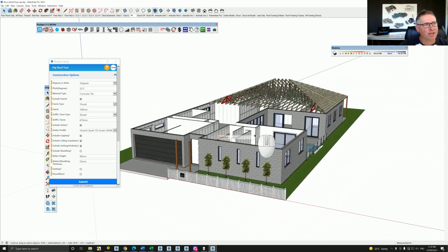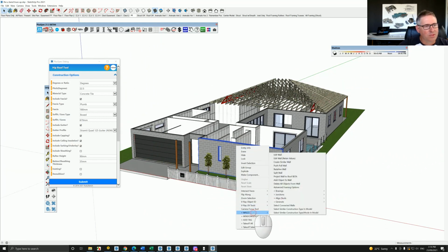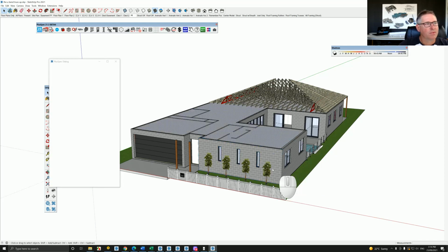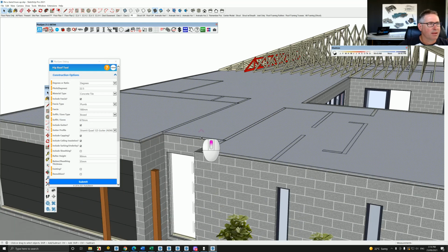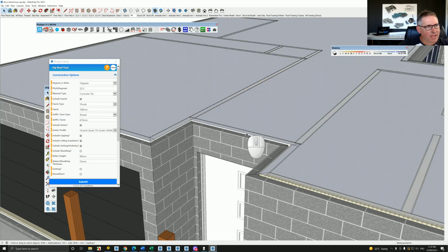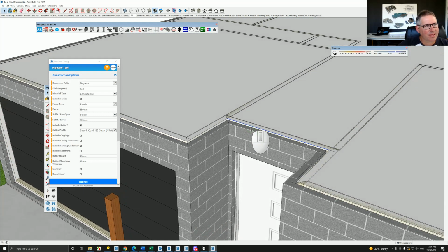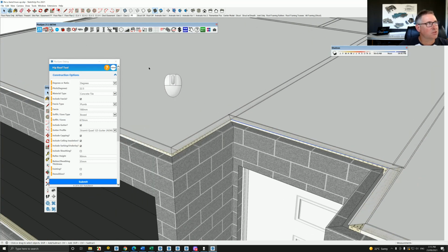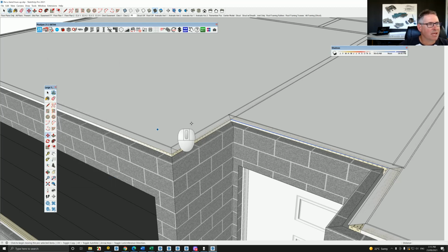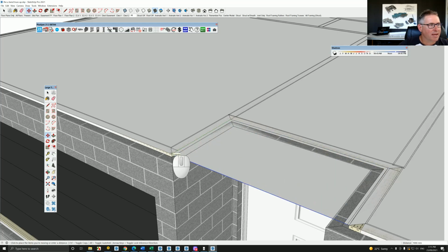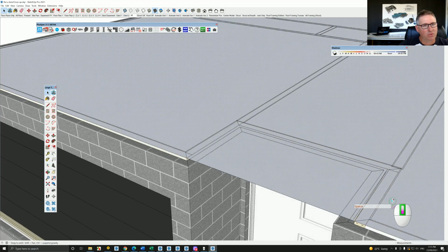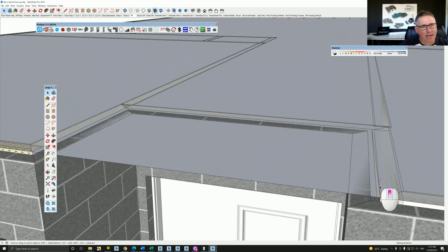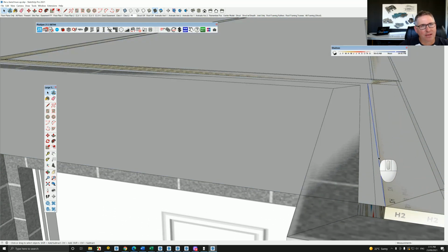Alright, I'm going to go back to scratch, right click, walls, generate roof from walls. Okay. And then what I'm going to do is I'm going to try and get the edge, right? You'll know before we spoke about edges and faces. I'm trying to get the edge, and I knew that the edge would line up with the outside of the wall, and therefore if I actually use my move tool, which is M as a keyboard shortcut, and I move it out to here, I won't have individual faces anymore. Well, I shouldn't, unless there's a straight line there, and this is what's happened here.